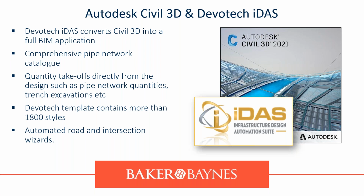So iDAS works directly in the Civil 3D interface. There's no need to open up another application and import, export, that type of back and forth. Everything is done in the interface. You can get your pipe network quantities, trench excavations as per SABS 1200 and so on. It has a ton of styles. I mean, 1800 styles, that is quite impressive. So you can really cater to what you would need, and you can also customize it if needed. They do offer those services.